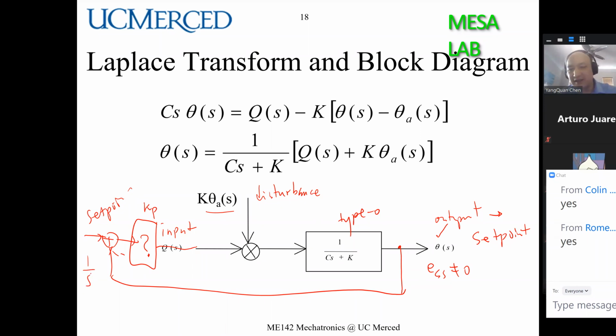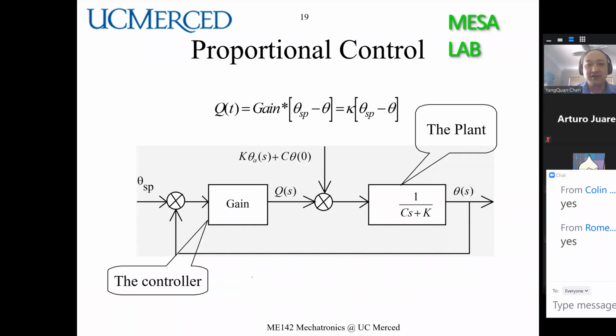So this S is what I call the generator of the signal. And this is not contained in the loop transfer function. So therefore, it's not satisfying the internal model principle. Therefore, the steady state error is not 0. You can prove it. So here's the way we can show. Very simple, okay? We'll put the KP here.